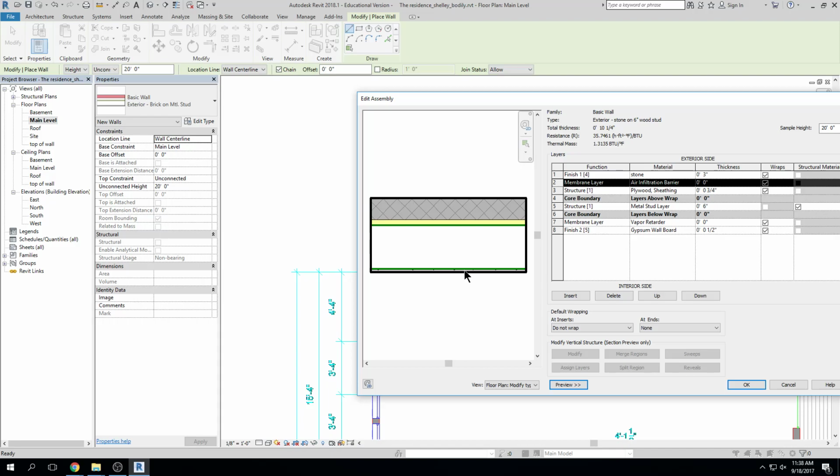How do you change the thickness, like on that? You click on it and it pops up as an option. It's not letting me. Oh, grayed out. You chose a stacked wall, I bet, to work with. Let me come back to you. Okay. Hit cancel, you're going to start over. Brian picked a stacked wall to mess around with. So we'll look at that in a second. Yeah, you have to cancel, get out of it. You're going to have to start with a different wall as your template. It's your template you chose. Sorry.